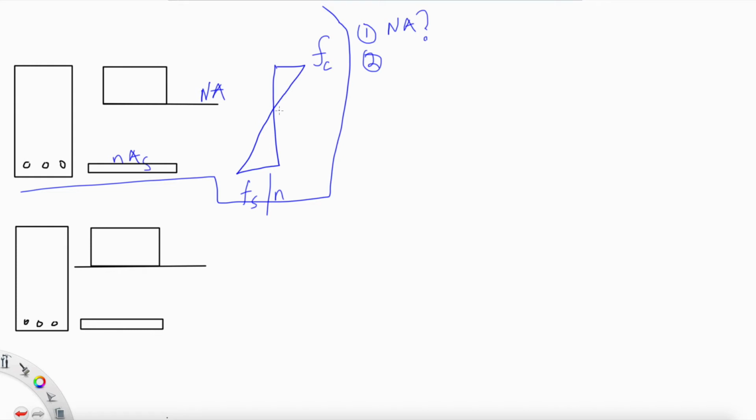So this diagram at a point can be something like that. That means the stress is taken by steel and the concrete is almost nothing. Most of it is tension and then it's just a small compression. So the neutral axis is somewhere here, in this middle point. Whereas in this one it's in the middle, and so on.